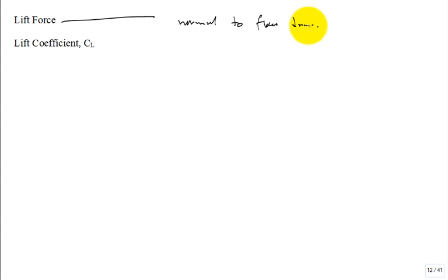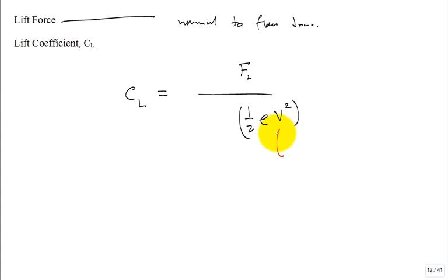Okay. Now, we had a drag coefficient. Now we have a lift coefficient, C sub L. It'll be the magnitude of the lift force, SI unit, something like newton, kilonewton. What do you think I normalize it by? What do you think we divide by? Dynamic pressure, 1/2 rho V squared. That V is called the free stream, sometimes V infinity, sometimes U infinity, sometimes cap U infinity, whatever. But that's what that fluid approach speed is, that free stream speed. And I need something else. What do I need right here? An area. But should I stand in front and look at the silhouette area in the direction of flow, or should I change my perspective for lift?